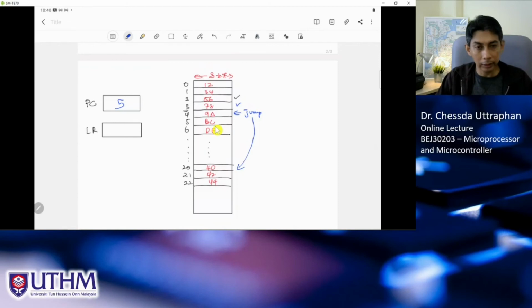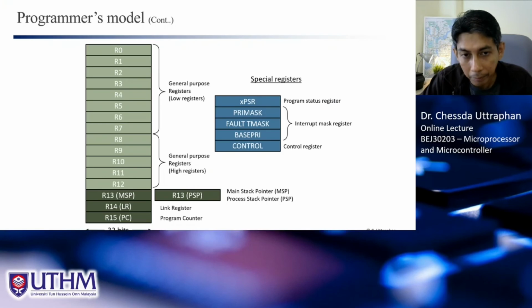But once you press a key, you interrupt the microprocessor to check what key is pressed and what to do after. Because you have many keys, the microprocessor needs to know which key you pressed. So there will be a small part of the program to check that, and if you press A, to display A in your Microsoft Word. That is what interrupt means.